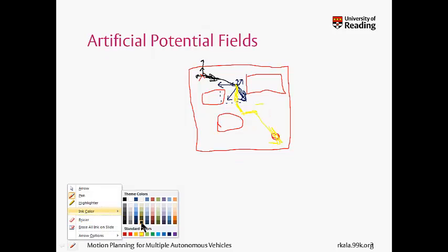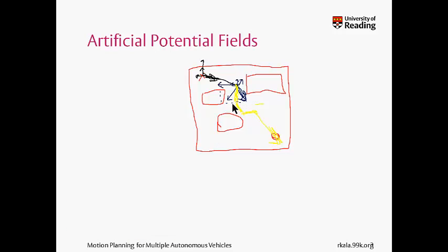Of course, in practice, when we apply these methods at any general point, say out over here, we sample the distances to only some points. So let me say I sample the distances to 8 points. So these are 1, 2, 3, 4, 5, 6, 7 and 8. These are the only points that the robot would be seeing. It will not see in any other direction. These are the only 8 directions that the robot will see, and of course it will always see the goal. It will always be attracted to the goal. So we sample the direction to 8 points, or sometimes a bigger ring is available with more points, and those are the only points in which the robot sees in its pursuit of the goal.